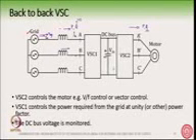But here you see the motor is taking some reactive power. So where does the reactive power come from? This reactive power is an energy exchange which is oscillating through the capacitor. The source VSC1 does not provide any reactive power, but VSC2 circulates the energy corresponding to this reactive power of the motor through the DC bus.